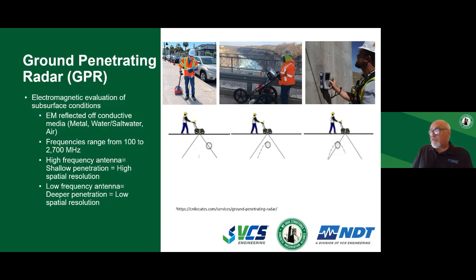And when we cross over these anomalies, we can pick up the location of them as well as the depth of them. Now, our frequency range in civil engineering applications, if we're in the soils, we're down at 100 megahertz as low, 200 megahertz, and 400 megahertz is our workhorse subsurface antenna. 900 megahertz is kind of a mid-range crossover frequency, but that's the range for low frequency. For high frequency, we're in the minis.